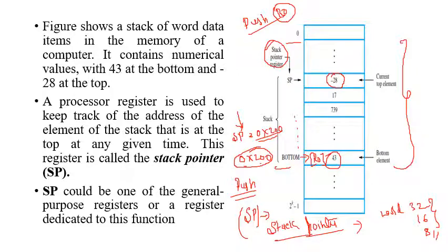Similarly, when you perform the push operation for the second time, push R1, or you can use push R0 again, let me assume push R0. When you perform the second instruction, based on the word length of the processor, for example, if it is 32 bit, the stack pointer will decrement by 4 because it requires 4 byte locations to store the data. So once you perform the push operation, the stack pointer value gets updated to 196.